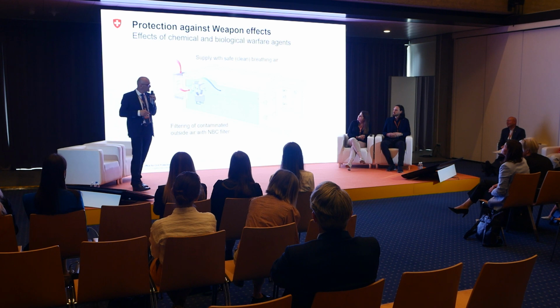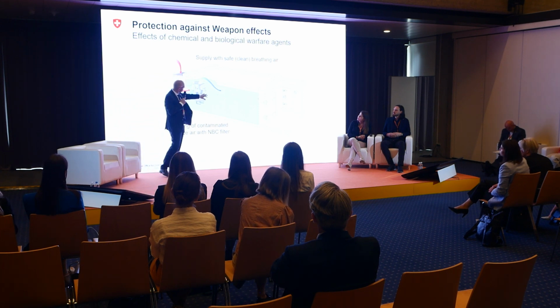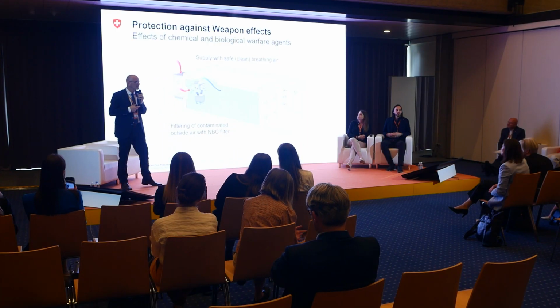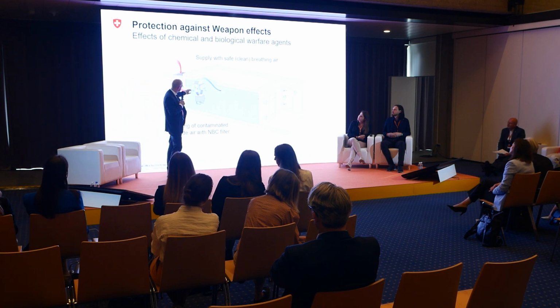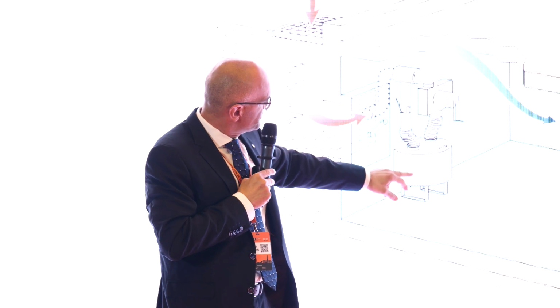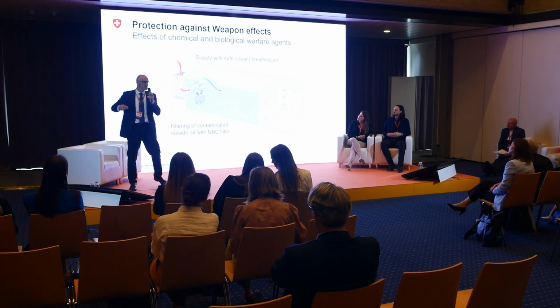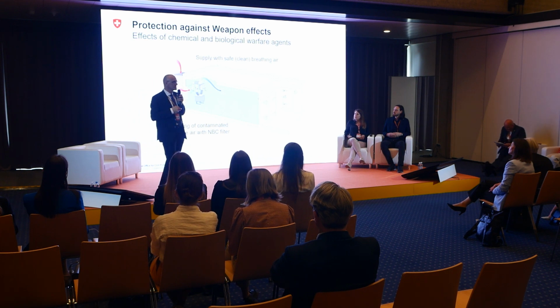Meaning then you need to have a filtration. So we have there a filtration system. Before, you have seen it was closed circuit there. You just used it for ventilation. If you have a chemical weapon attack or gases attack, any gases attack, you go through a carbon filter. That's a hugely dimensioned carbon filter with aerosol filtration as well.